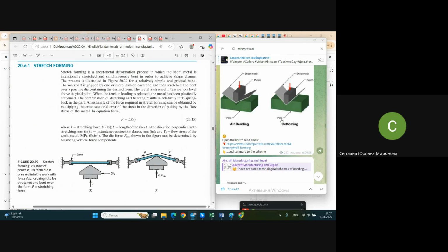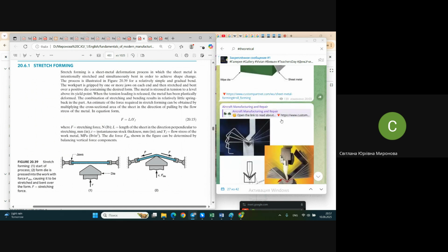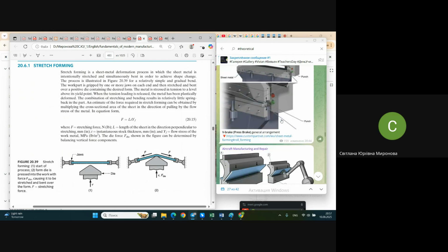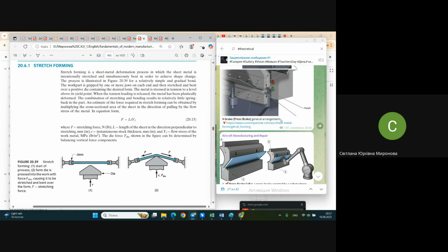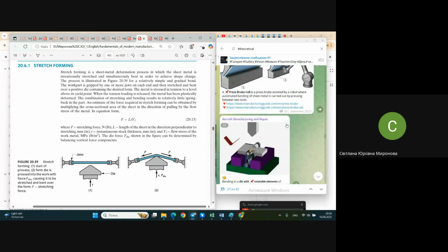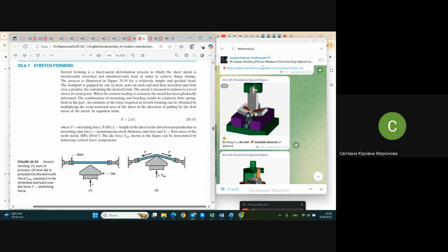And of course, it has a spring back effect afterwards. This spring back effect is solved by rolling back and forth several times, in order to make more significant plastic deformation in the workpiece, which corresponds to the finally necessary shape.